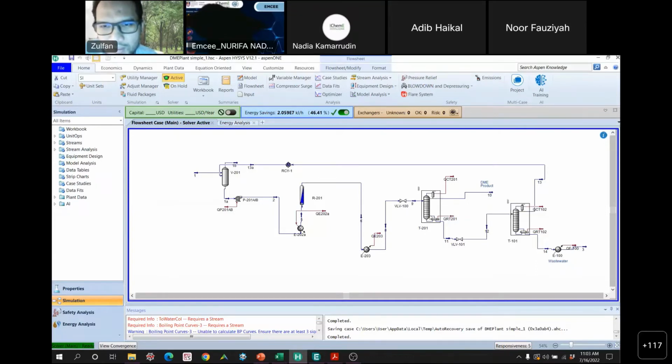So this is then DME, and then what goes down is water and methanol, and they are separated in the second column. Water goes down, and methanol, at about 60 degrees C, goes up as a distillate and is then recycled to the tank. So we have now